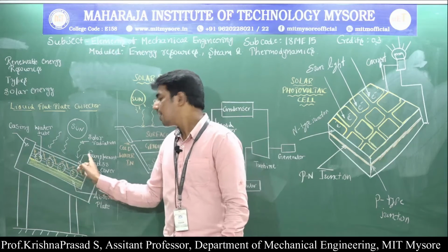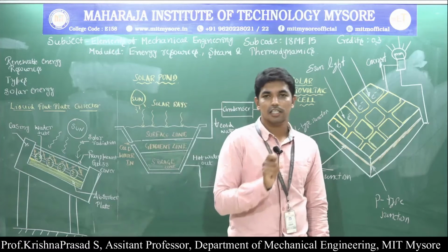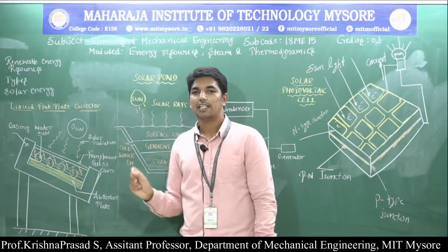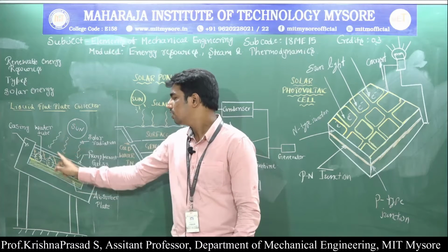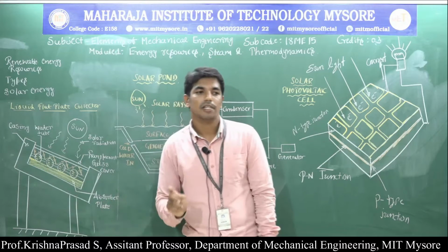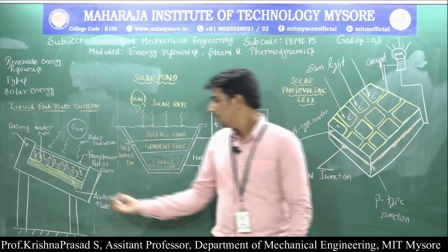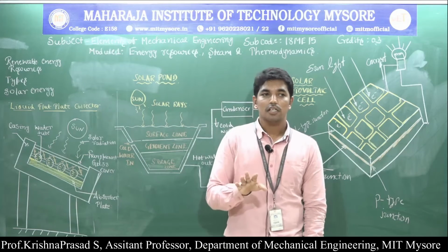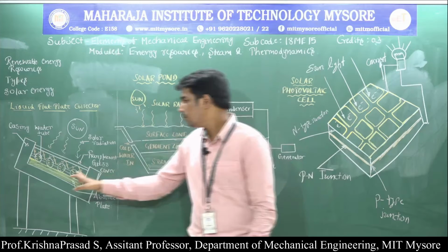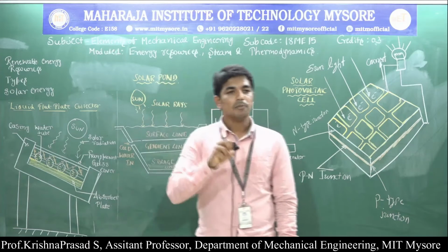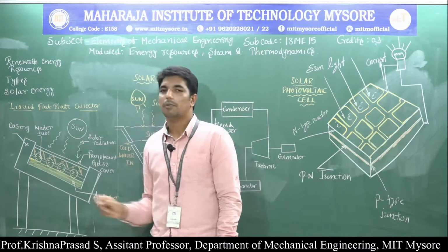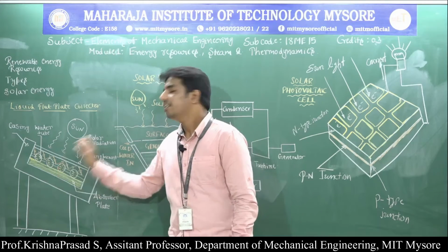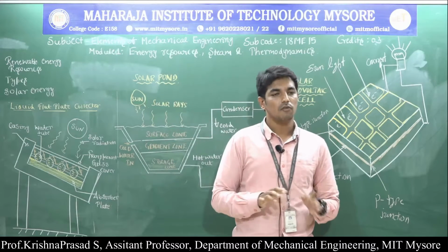The third one is the transparent glass cover. It is toughened glass with a sufficient thickness. Whenever solar radiation passes through this cover, it is incident on the absorber plate, and a few of the radiations get reflected from the absorber plate and would escape into the atmosphere, but the transparent glass cover does not allow this. It captures those radiations and reflects them back to the absorber plate. That means heat remains trapped in the air space between the absorber plate and the transparent glass cover, which means complete utilization of solar energy.